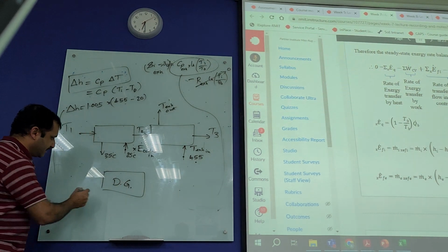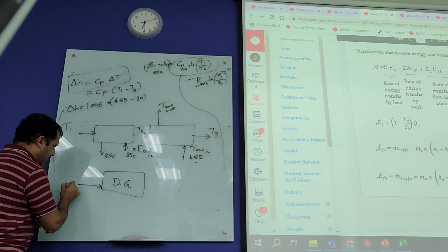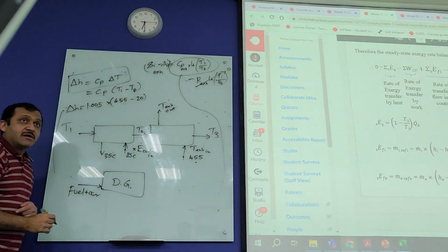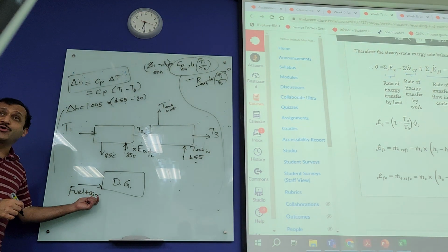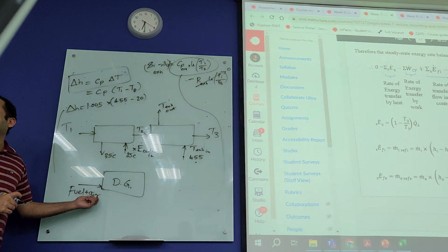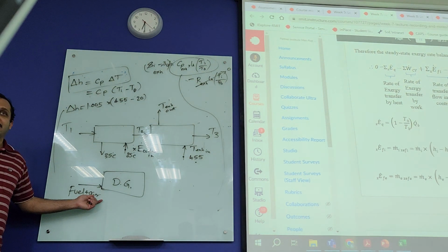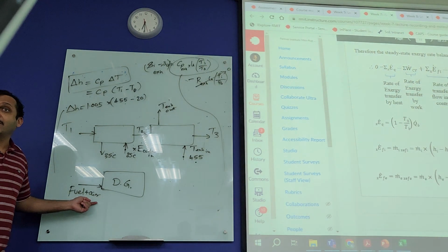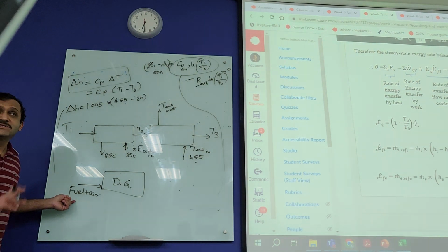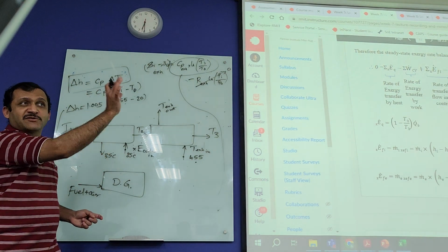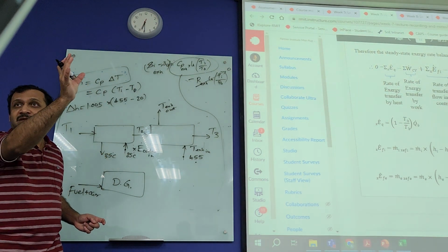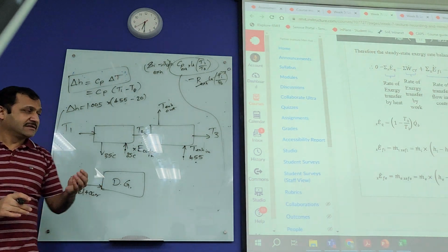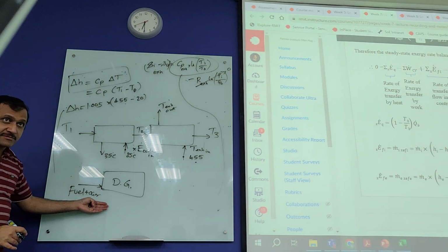That's your diesel generator. What's going into the diesel generator is fuel plus air. The question already says to ignore any exergy that air is bringing in because air is already at dead state. So there's only the exergy coming from fuel. Have you already calculated exergy from fuel? Step 1, which is mass flow rate of fuel times the calorific value, which I showed you just before when we calculated the mass flow rate of diesel. So exergy is going in.